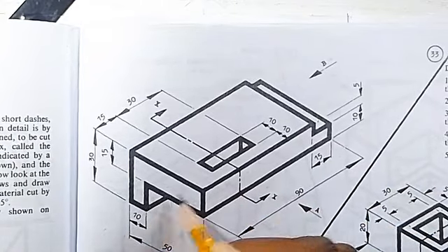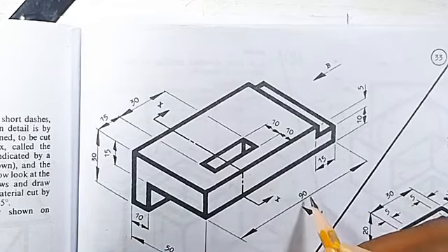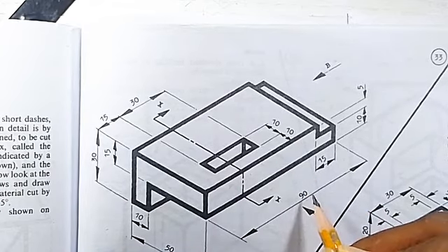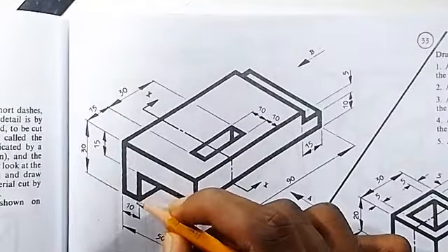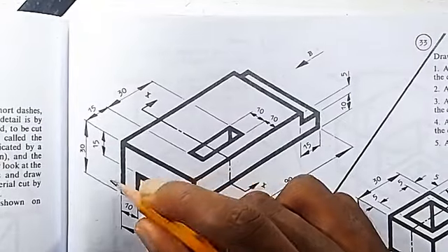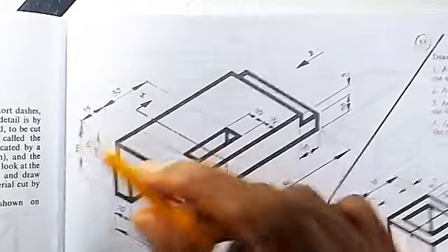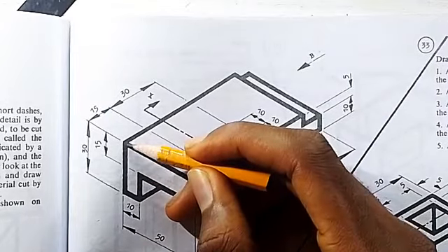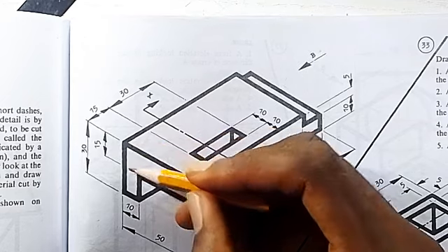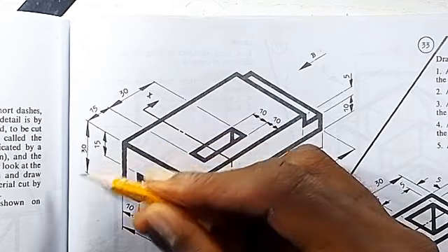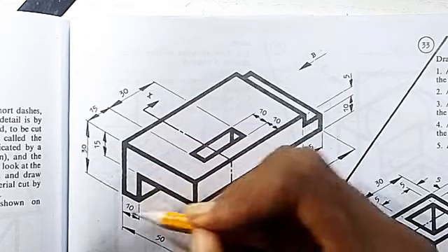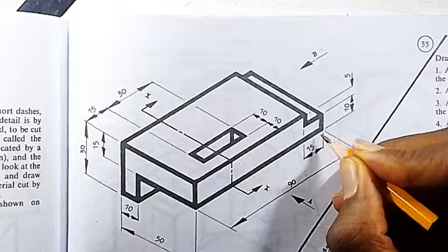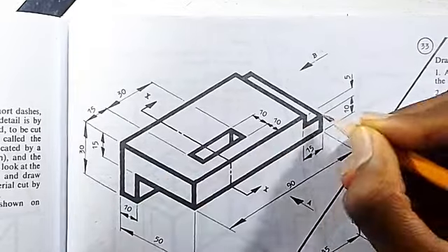Remember, this is running through to the end, and the total length is 90 mm, which is 9 cm. So draw a line of 9 cm. After doing that, we take this line up by, it's not given the length. So what do we do? The total length from here to here is 30, which is 3 cm, and from here to here is 1.5. So 3 minus 1.5 is giving us 1.5. So you draw 9 cm, then take the height 1.5, join it again.